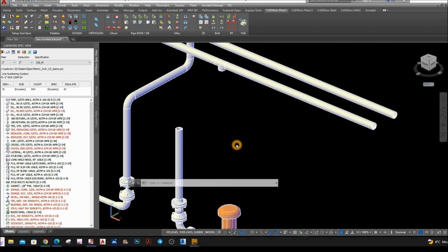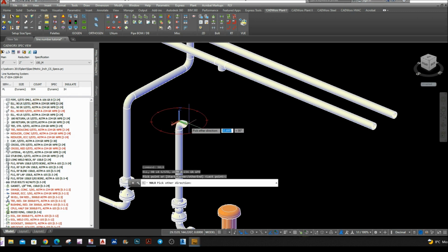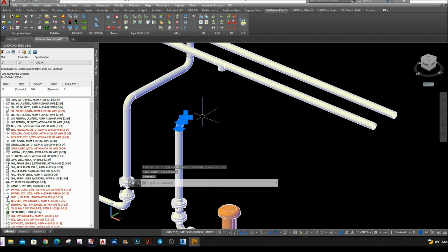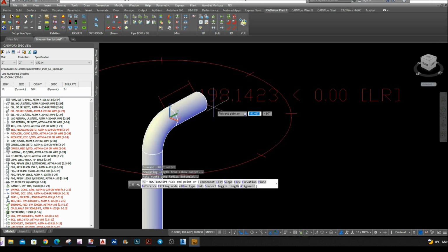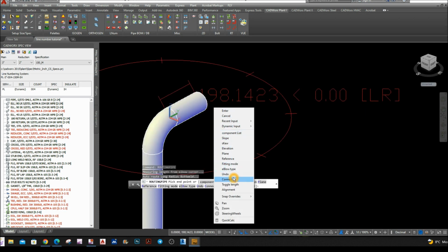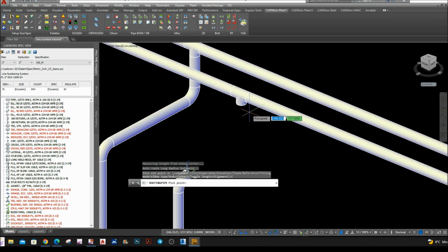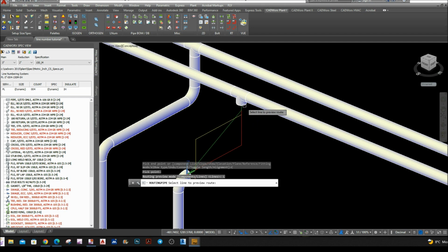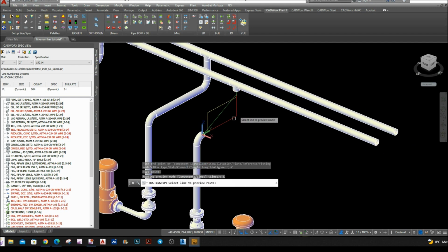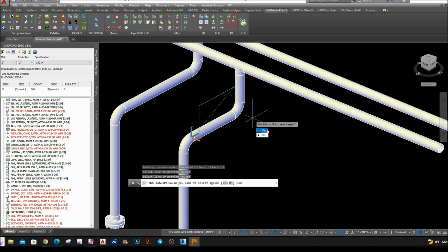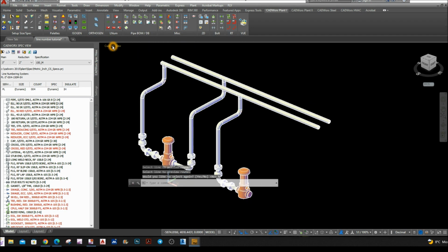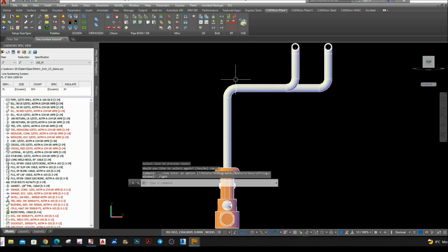So now if I use connect command, Cadworx will provide two possible routing paths indicated by different colored lines. So what I'm gonna do is attach, maybe start with elbow first here, and point it to that direction, and snap that elbow. Click that plus sign there, right click and select connect, and click this endpoint here by the branch and select lines, and you can see the routing path here. I'm gonna select red, enter, and select no. Now I'm just gonna check by bringing this to right view. Yeah, it's parallel.